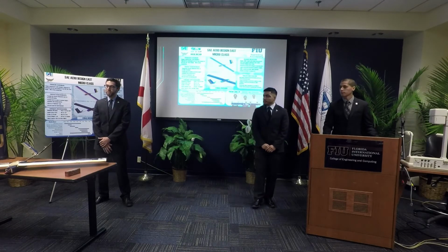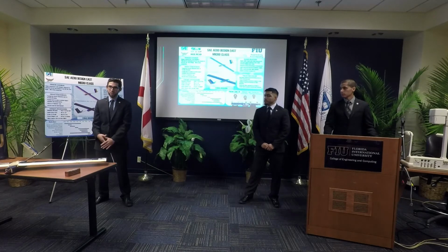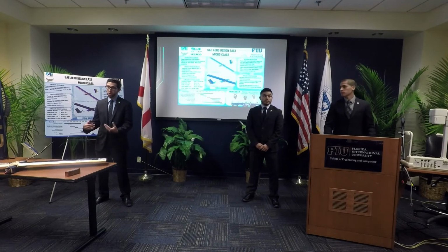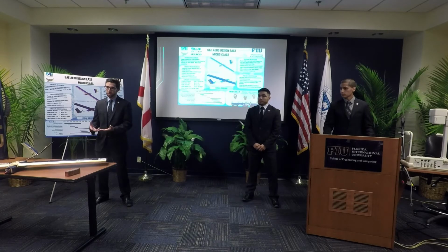Okay, so the flying wing had a dihedral built in originally. This one, we didn't want to do it because of the way we were going to connect the wing. Initially, you saw we just assembled it using rods and tubes. By accident, I will admit, because the deflection of the wing is relatively high, it gives it an effective dihedral line. So we just stuck with it at that point.